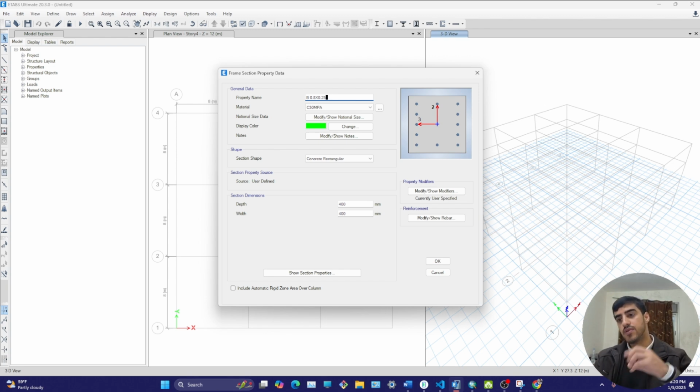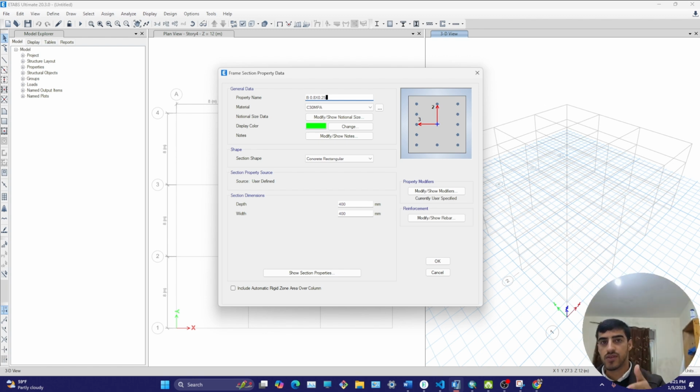The thickness of the beam would be the same as the thickness of the slab. So assume we have 25 centimeters, or 0.25 meter, thickness of that slab. So I assume the beam is hidden in the slab. It's not dropped. So I have 0.8 width by the thickness of the slab, 0.25.